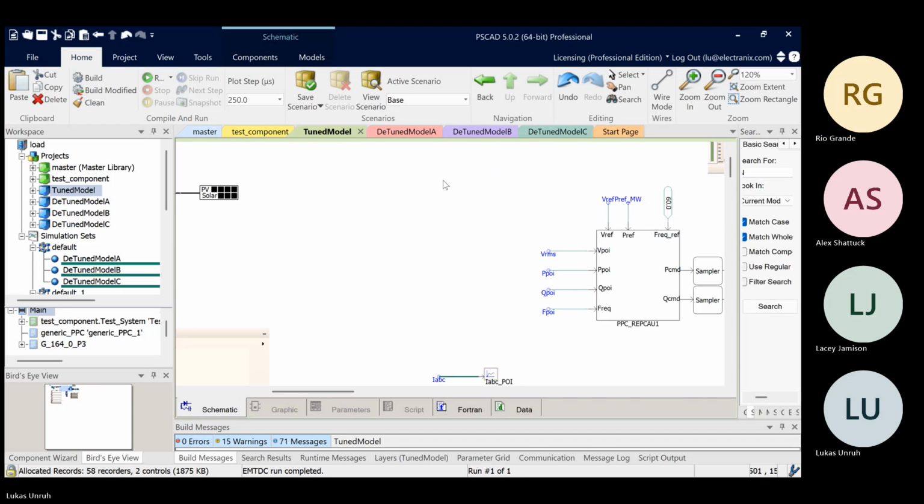Can the PLL be correctly represented in the phasor domain simulations? I read some articles saying that if you represent it, even in a simplistic way, it could help in weak grids. Yeah, so there's been a lot of work done in that domain, right? Trying to get some PLL representation into the generic models.